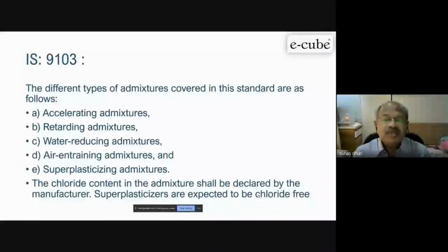So whatever water we are using to make the admixture has to meet the requirement given in the particular standard, especially for the chloride content. You cannot use just any water, otherwise you will take sea water and make the admixture with that. That is not useful for concrete. And one advantage of chloride is that you get setting acceleration, meaning you can get early setting. That is the cheapest accelerator admixture available. You can get early strength from that.